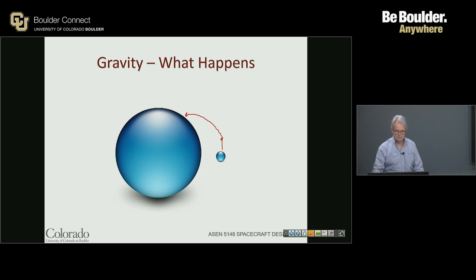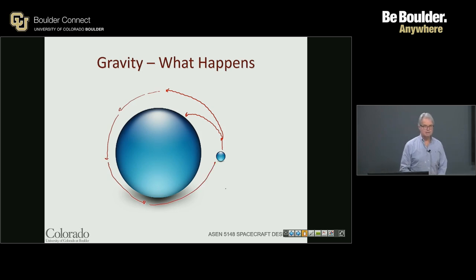And what we're looking for is the condition where gravity always pulls this around, but not enough to get it back onto the Earth. I think in Brown's book he refers to this as Newton's cannon, where we finally have a spacecraft in orbit that has enough velocity where it doesn't get pulled back to the Earth, nor does it leave the Earth environment as well. And so we know that the velocity expression for this is just the square root of mu over r.